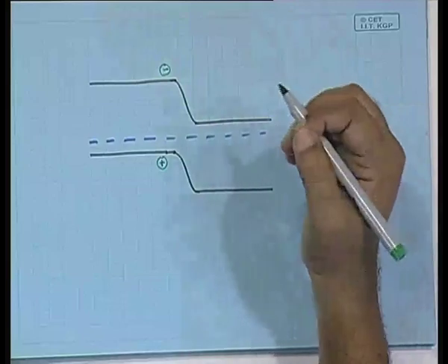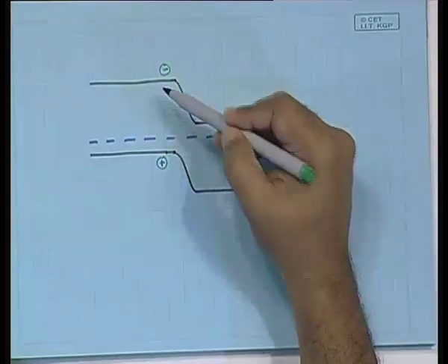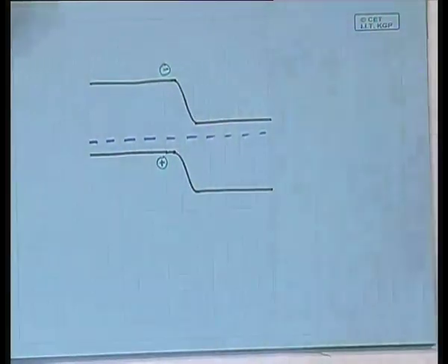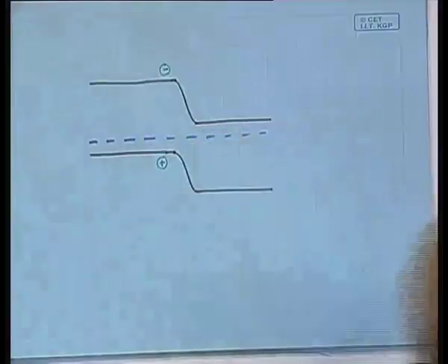So, electron hole pairs are created, and imagine that one electron hole pair is created somewhere here. Do you understand why the electron hole pair was created? Essentially, if the light has an energy bigger than the band gap energy, then it knocks an electron off its site in a particular atom, makes it freely movable in the bulk material. As a result, the electron goes to the conduction band, leaves behind a hole which is also free to move, that is in the valence band. So, suppose it has been created here.